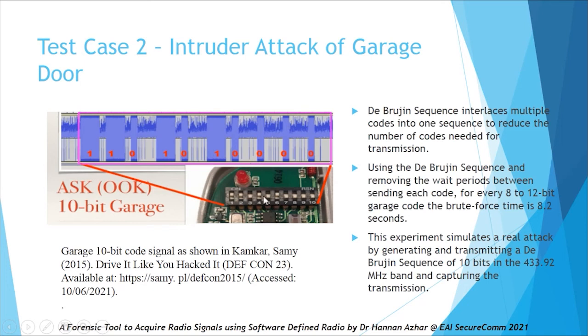So the whole experiment was inside a Faraday case, to avoid legal issues, to ensure that transmitted signals are contained and do not interfere with any other devices. And it was very low power as well, so we could do this experiment. And because it was confined, the GPS receiver was not effective, because no signal was outside the Faraday box.